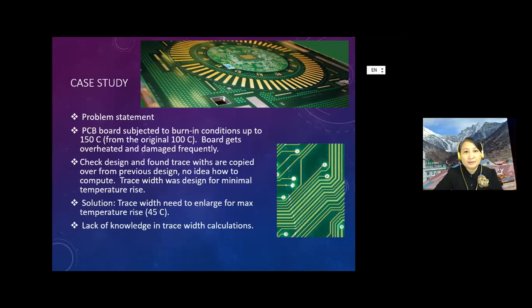And so based on the results, we'll see that of the participants, almost 45% are doing more than 10 layers. Which means that you have to be really careful with doing the design because they are usually a lot more complex, right? And then of course, do you decide on the PCB stack-up? So we have about 85% making decisions on your PCB stack-up. So you might want to know what's a balanced stack-up or what contributes to an unbalanced stack-up. And the last item is, do you have any controlled impedance?